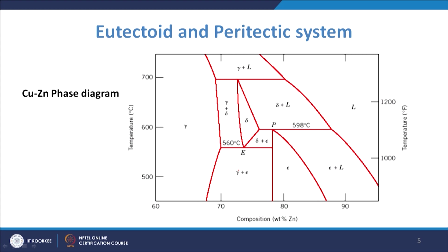As you come down, you will have different reaction products because the solubility will be different as the temperature changes. If you talk about other systems, like the copper aluminum system, there also, when you are in a higher temperature zone, the solubility of one phase into the other is more, while when we decrease the temperature the solubility is decreased. So, what happens, the supersaturated phase will again precipitate, and this concept is utilized for bringing in hardness, that is known as precipitation hardening.